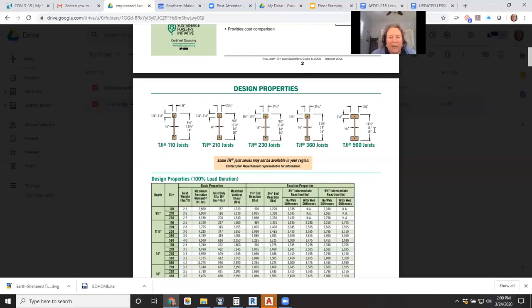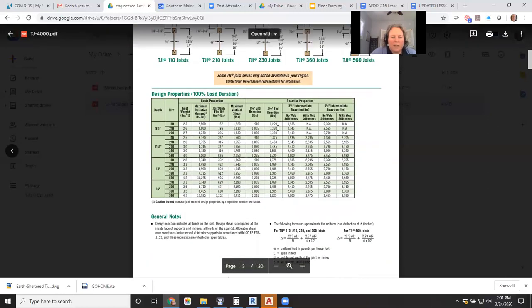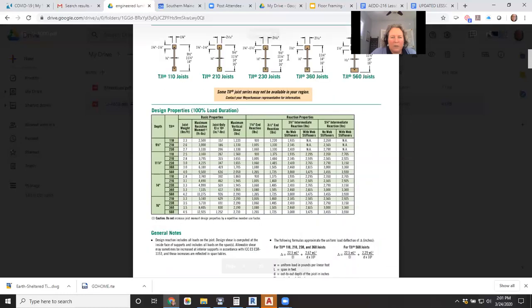16-inch floor joist depth is pretty deep. But that's a whole other ball of wax. When you start to design your full building section, you have to take into consideration that's a huge amount of plenum space that is being taken up by your floor plate, 16 inches. So that's critical information for you all.